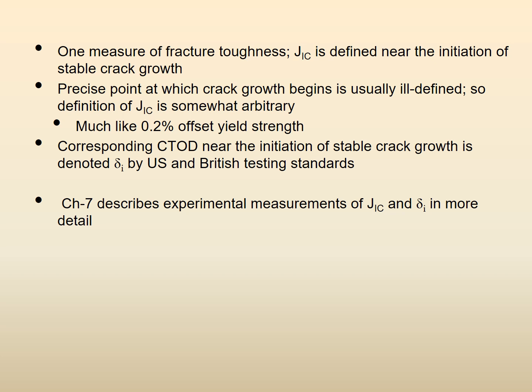That is the experimental procedure for fracture toughness measurement, not the general J1. J1 is the J integral at any load, but when the load becomes the critical load or the A becomes the critical A, then we call it J1C. Similarly, delta, the CTOD, is at any load or any crack size, but when it reaches the unstable region, it becomes the critical value.